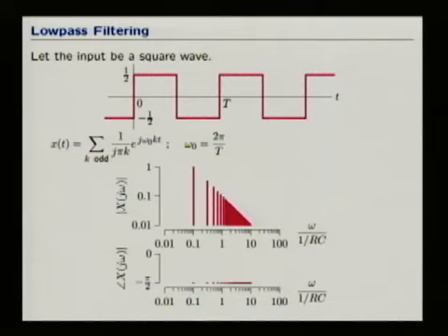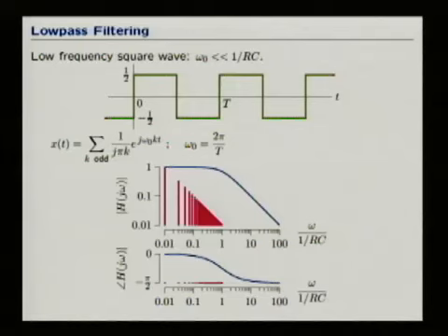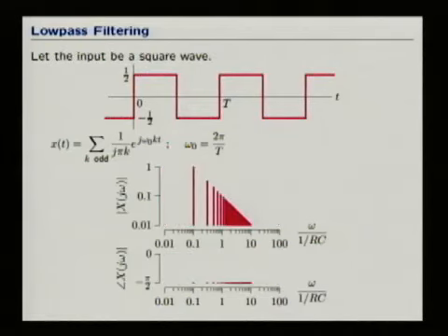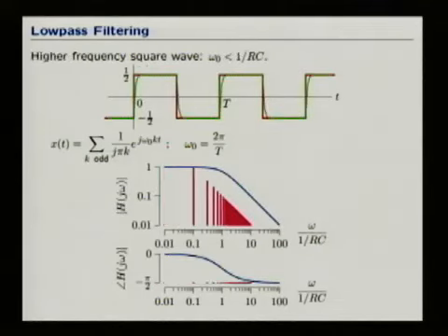And then if you can break the signal into Fourier components, which was easy when we had a Fourier series, then it's easy to calculate the output as the sum of weighted and possibly time-shifted versions of the components of the input. So we can decompose the square wave into a bunch of Fourier components, and then think about how they pass through the filter.